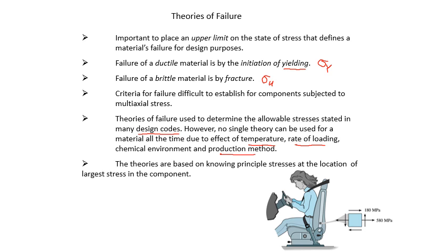And the theories are based on knowing principal stresses. That's why we discuss this after stress and strain transformation. So we need to know principal stresses, and these principal stresses need to be known at the largest stress components, meaning critical points where you have very large stresses, especially if you have stress concentration.